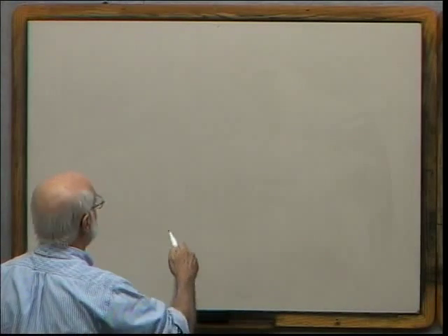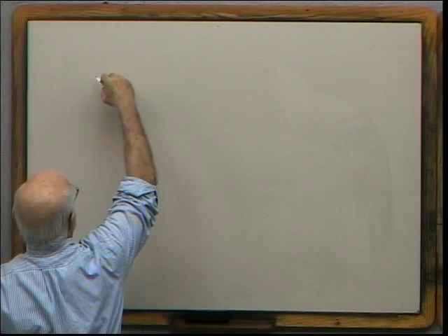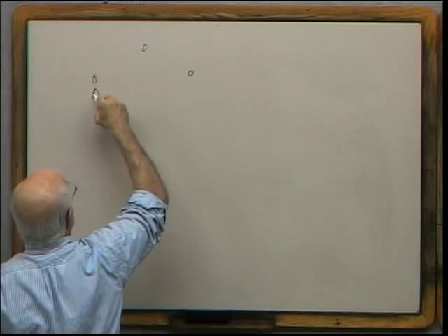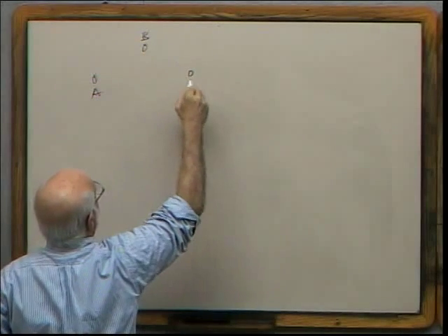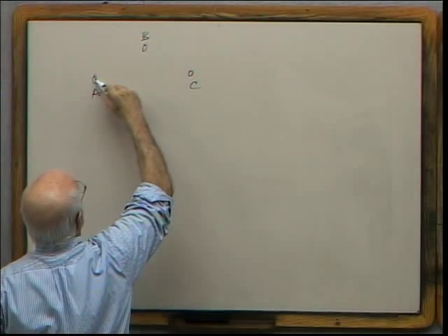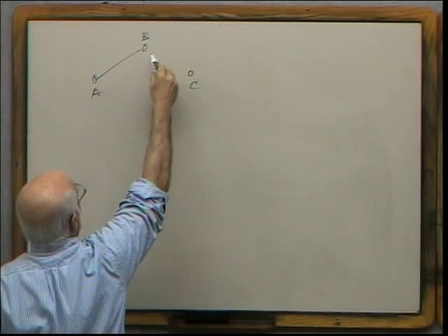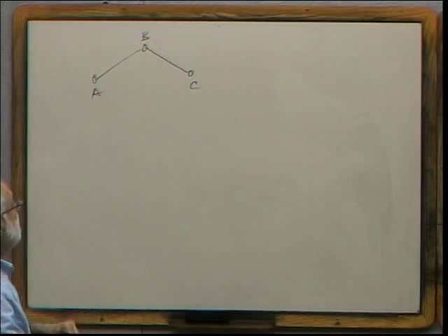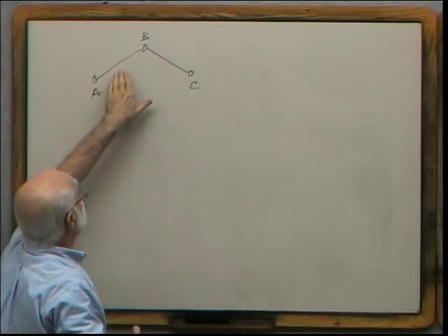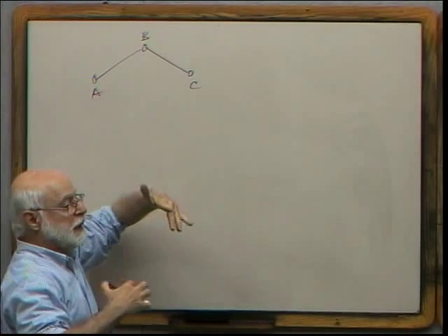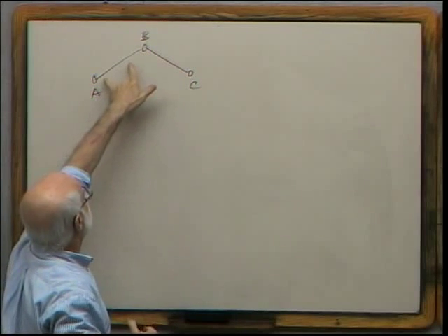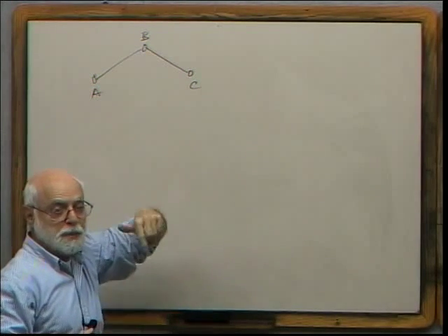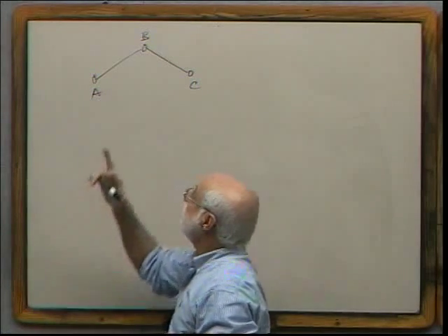Here is a simple example: cities A, B, and C, with a bunch of trunks, or servers, connecting A and B, and a bunch of trunks connecting B and C. If I looked at each trunk group in isolation, assuming the only traffic was between A and B and between B and C, and blocked customers are cleared, then this is just two Erlang B systems.